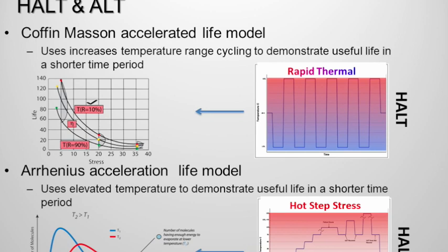You will know what are the temperatures that cause absolute failure. And knowing these ratios between that and the normal operating temperature can help you select the right temperature that you are confident you're not creating failure modes or destruct levels that would not commonly occur in the field. So you can see how doing HALT in conjunction with these greatly benefits these accelerated life models.